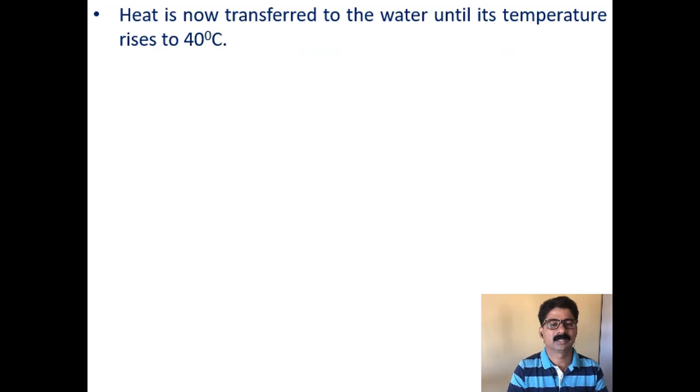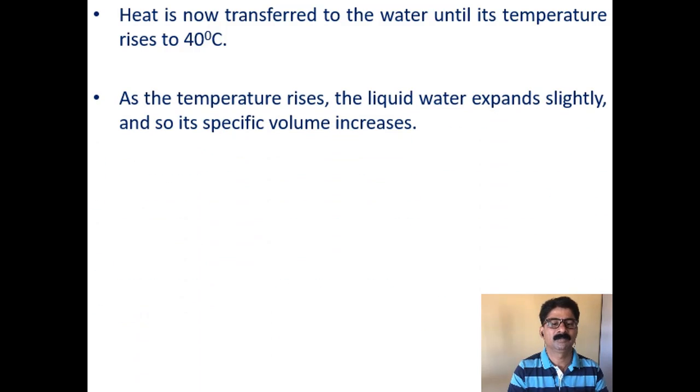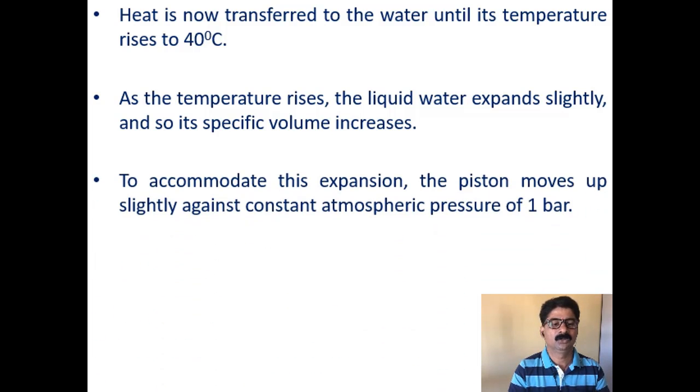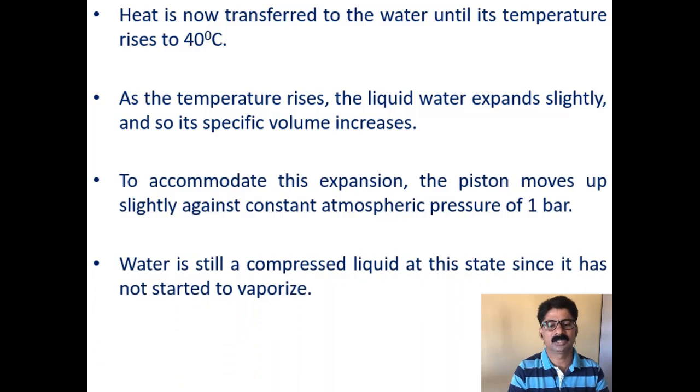Now heat is transferred to the water until its temperature rises to 40. As the temperature rises, liquid water expands slightly, so its specific volume also increases. So that also you should know, as the temperature is increased, volume also increases slightly. To accommodate this expansion, the piston moves up slightly against the constant atmospheric pressure of 1 bar, because the cylinder is fitted with the piston.